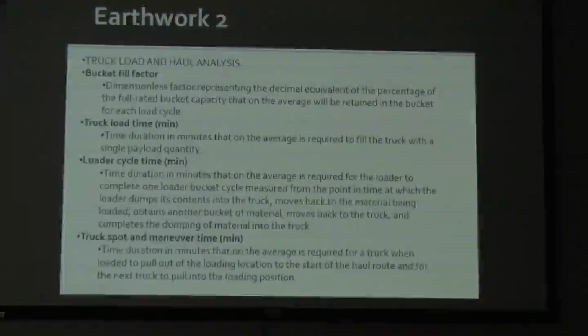Truck load and haul analysis. The bucket fill factor is a dimensionless factor representing the decimal equivalent of the percentage of full rated bucket capacity that on the average will be retained in the bucket for each load cycle. The truck load time is the time duration in minutes that on the average is required to fill a truck with a single payload quantity.